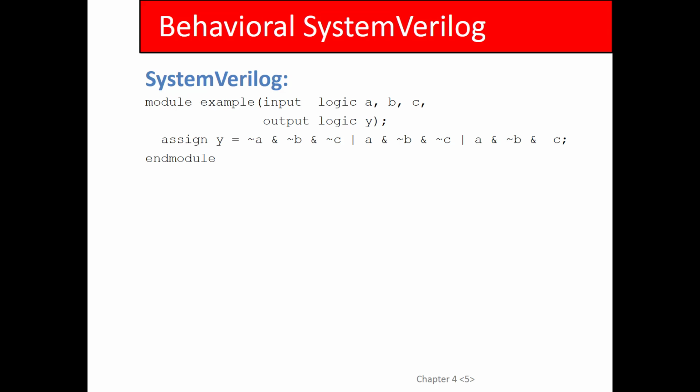The only difference is in real hardware, it would happen after the propagation delay, and in here it's going to happen in an epsilon time because there's no propagation delay listed, and Verilog doesn't know what the propagation delay is because that's technology dependent. So this is only behavioral, right? Make sense? Right?